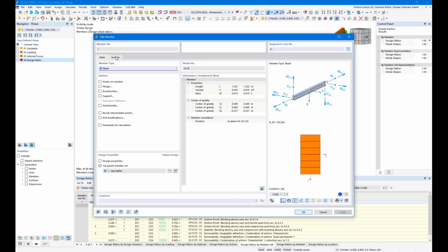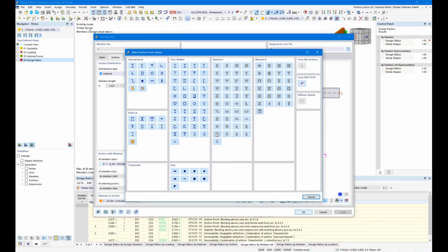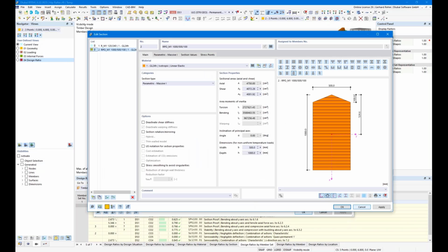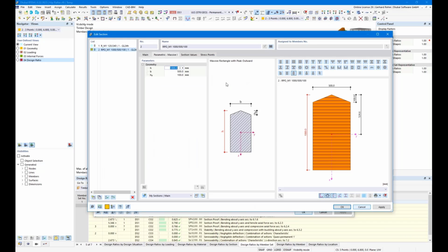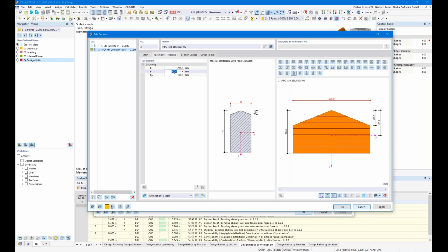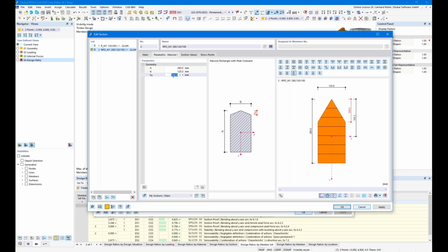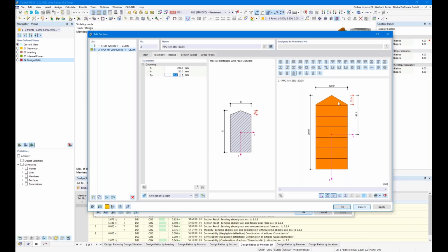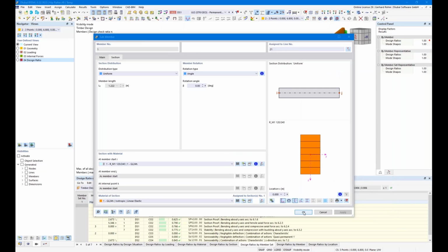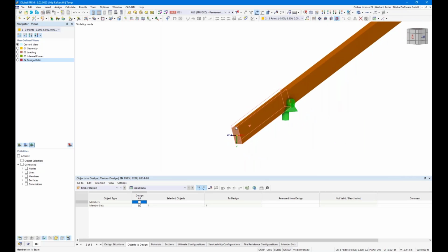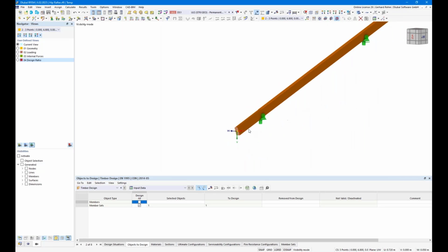And so maybe let's create one example here quickly. You should have the time for it. Here we will change this to 200, maybe 280, and the width was 120, and this one should be 35 millimeter. Of course, you need to calculate the correct angle and then the correct height of this reduction. Okay, so let's change this. Here we go. And now the question comes up, what about the stiffness? Is the stiffness correct by considering it without the notches?